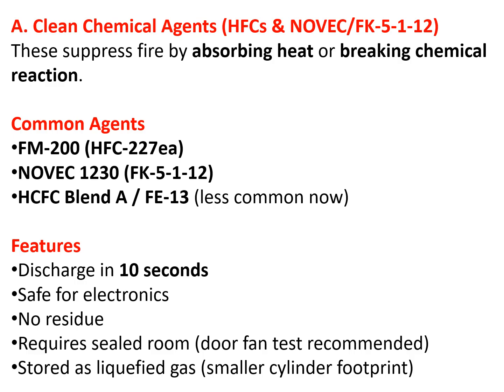Common clean agents are FM200, that is an HFC 227EA, the chemical formula. Second one is Novec 1230 and HFC blend, less common now.